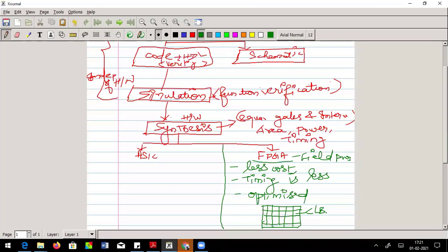Now I would like to change my design and make it something like an up-down counter, right? Then again I go and resynthesize this particular code and fuse it on an FPGA. Now my FPGA will be acting like a storage mechanism with D flip-flops and goes through a counting process. So this is the facility that is available with this FPGA. In fact, every CLB has a facility to compute combinational logic as well as sequential logic. That's the beauty of these CLBs.